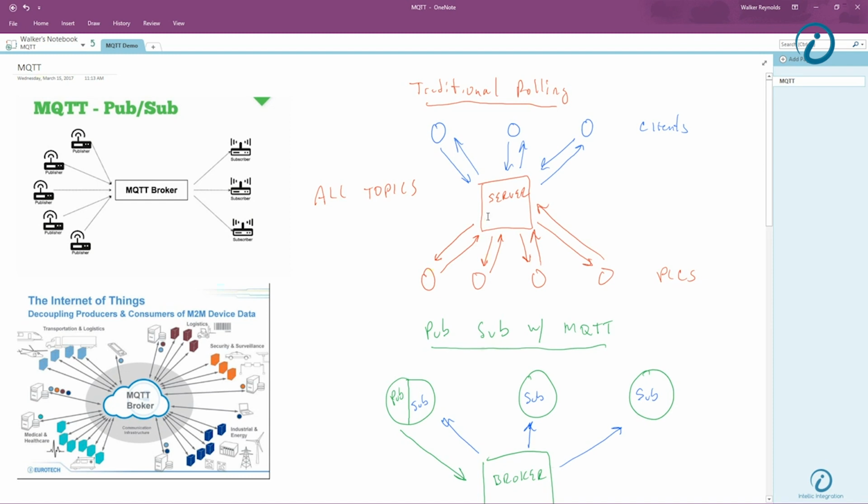First off, it's incredibly inefficient to do a round-robin polling to all the PLCs we have in the field. Also, I've got to do configuration everywhere. If I want to get tags up here in my clients, whether this is Wonderware or Ignition or FactoryTalk, it doesn't matter what we're using up here, I've got to do some configuration for my tags, unless my tags are browsable and I can drag and drop them from my OPC server, browse my server and drop them in.